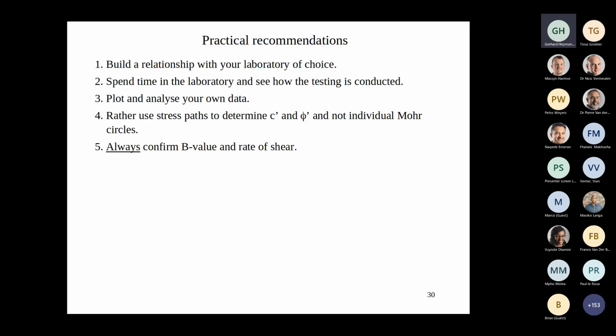And there are ways that we can do an area correction for shear banding, but you know what? I think one needs, as an engineer, to do a reality check, and we have to be honest with one another and say, you know what? The moment that shear banding starts to occur, everything that happens after that, the stresses that you calculate from the boundary conditions are going to be wrong. Yes. And I can put it more diplomatically, but let's just say it as it is.